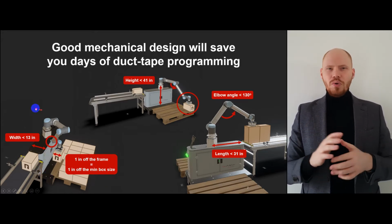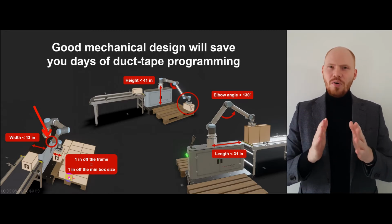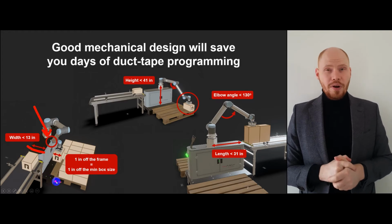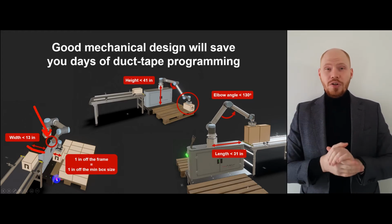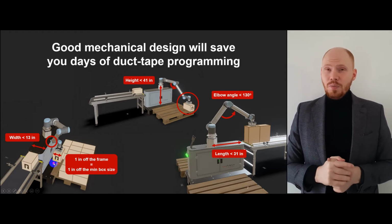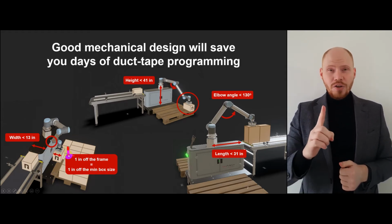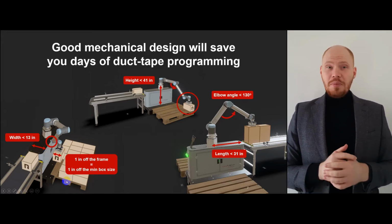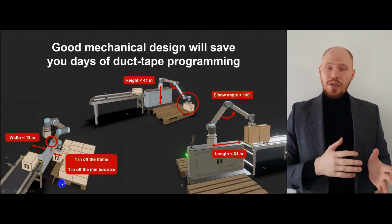As a general rule, you want your frame as narrow as possible, as it directly constrains the working area of your robot. Another observation is that every inch cut off the frame gives you space to place a box 1 inch smaller. So it's quite impactful. A good example of a problem you can see on the slide.